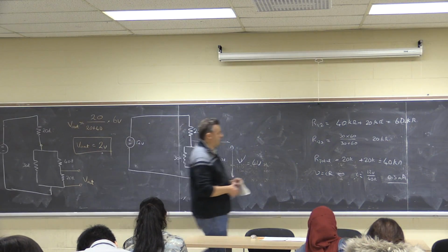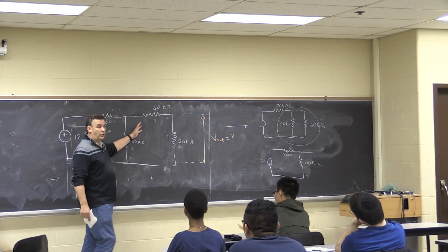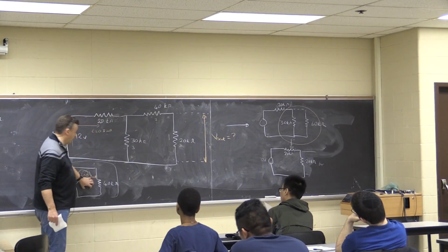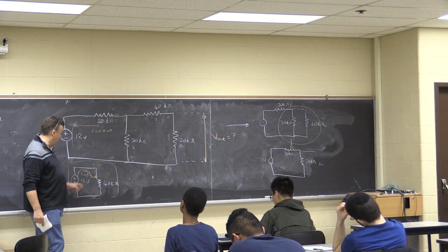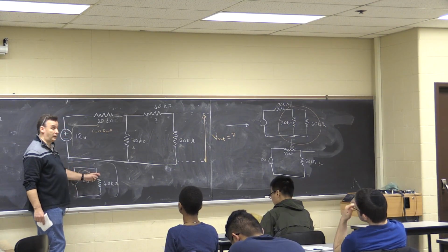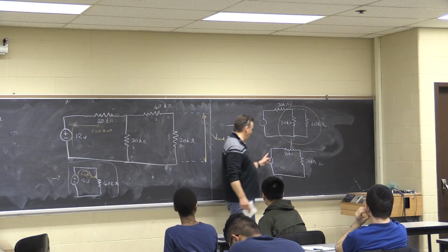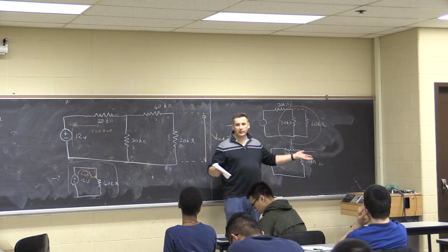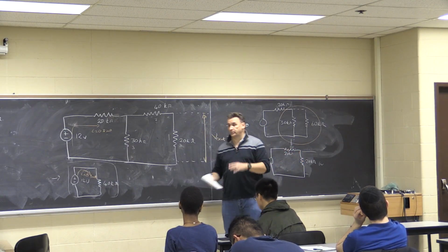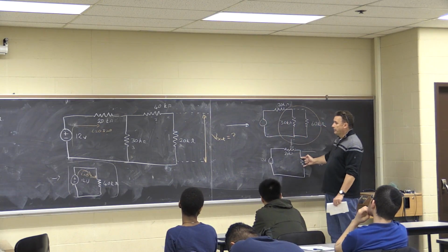Okay, so I'm running short on time, so maybe I went a bit quickly. Let's just quickly recap on what we did. We simplified this circuit, series parallel combinations. That gives me one resistor. Across that one resistor, I know I dropped 12 volts, and it's across 40. I can work out the current. But I also know the voltage and current division rules. In this case, I've got two 20s in series. Voltage division tells me same voltage across both. So 6 volts and 6 volts.